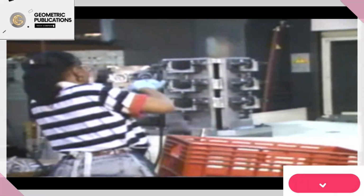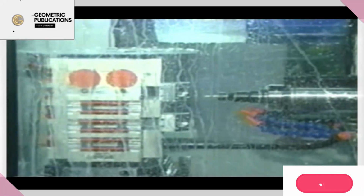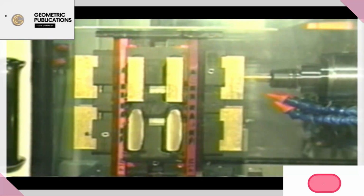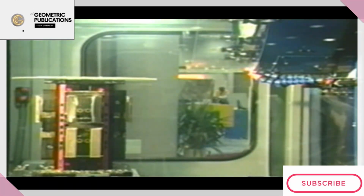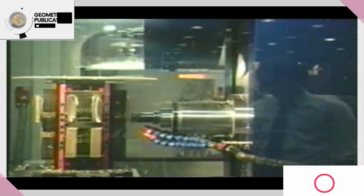Tombstones, commonly used on horizontal machining centers, come in a wide variety of configurations to hold multiple parts. The part program is written to machine all parts on the tombstone before shuttling it out of the machine. Setups on machining centers often utilize multiple vices in a variety of arrangements to get more parts done at a time. Multiple vices may be arranged on an indexing device to further expand the parts carrying capacity of the machine table. These often work in conjunction with rotary tables.